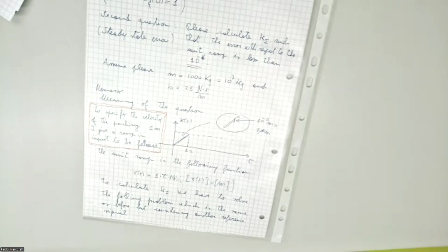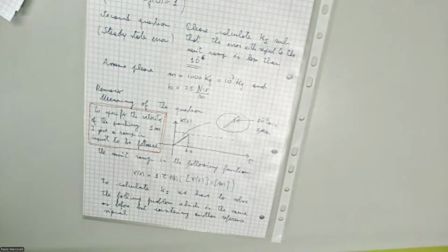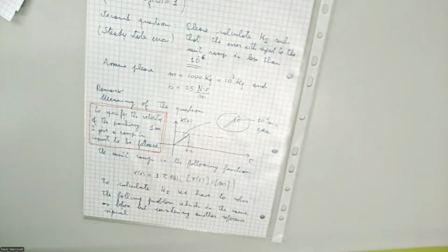This means the distance of the wall when I start the auto parking should be larger than 1 meter. If the sensor measures 1 meter 10 centimeters, it sets 1 meter in order to park. The parameter H is responsible for this precision. We don't need H. I mean, H equals 0.